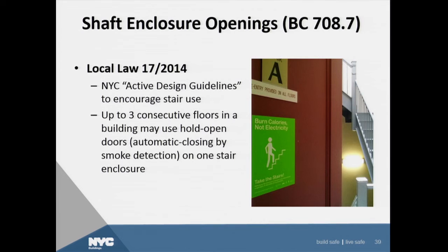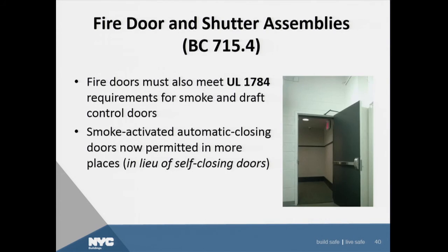So they're encouraging now exercise in the workplace. Some offices just want it. So if you have 3 interconnected stories and you don't want people using the elevator, and actually at 280 Broadway we do this as well, you can use self-closing doors to have the doors go shut. So they could be held open, but in the event of a fire, upon activation of smoke, they can now shut. And this is again new to the 2014 code.